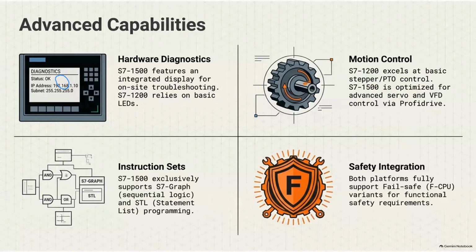S7-1200, sorry, S7-1200 excels at basic stepper or PTO control. Although it says that here, the processor will be the same and the logic will be the same. As for the PID controllers that are used, very recent PID controllers have neural network logic within them, and we are not calling that a PID controller, we are calling it an advanced controller. And these advanced controllers are present in S7-1500.